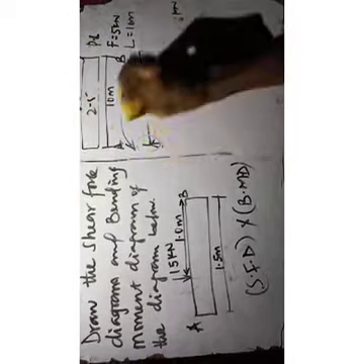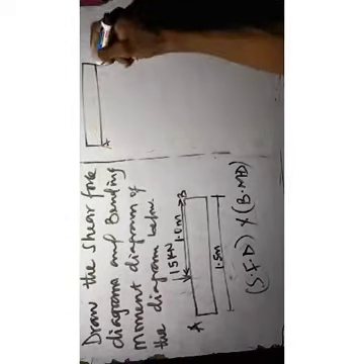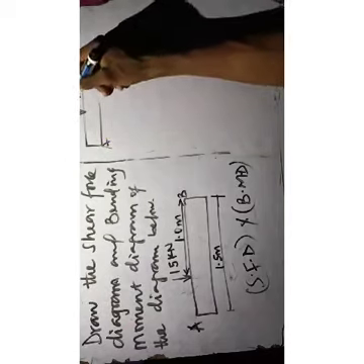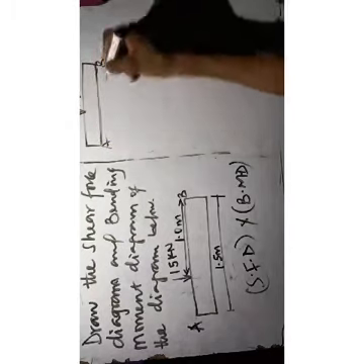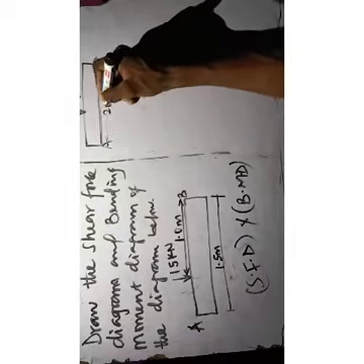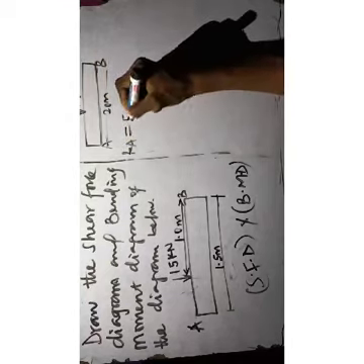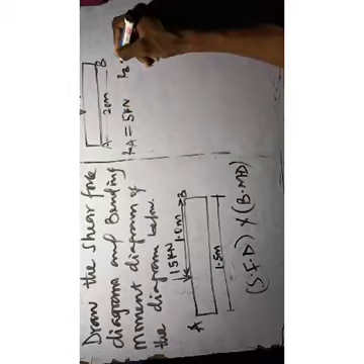Very fine. Now let's consider this question as a classwork. Let's say we have our distance here, point A, point B, and we have 10 kilonewton here. The total distance is 20 meters. So what will be your RA and RB? Don't guess, be appropriate. RA will be equal to 10 divided by 2, regardless of the distance. That will be 5 kilonewton. RB is 5 kilonewton.